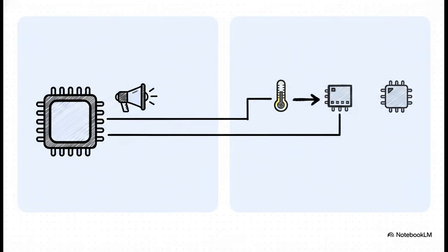Now on this bus, every device has a very clear role. There's always at least one master, think of it as the director of the movie. It's typically the main microcontroller, and it's in charge. It generates the clock pulse, it starts the conversations, and it ends them.